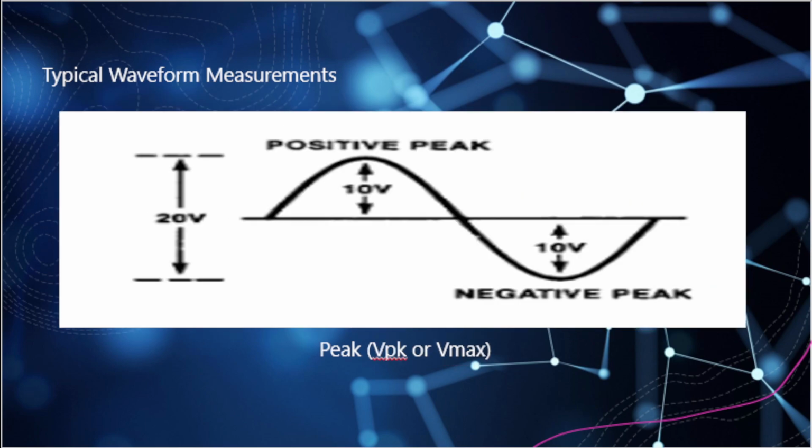What's another? We have peak voltage. In peak voltage, you're only concerned about one peak, either on the positive slope or the peak on the negative slope. Why do we care about a peak measurement? Well, if our peak to peak is 20 volts, but our single peak measurement is showing 9 here instead of 10, and 11 here instead of 10, then our signal could potentially be not symmetrical. Which is also why it's important to set up your oscilloscope correctly so you don't come to that conclusion.